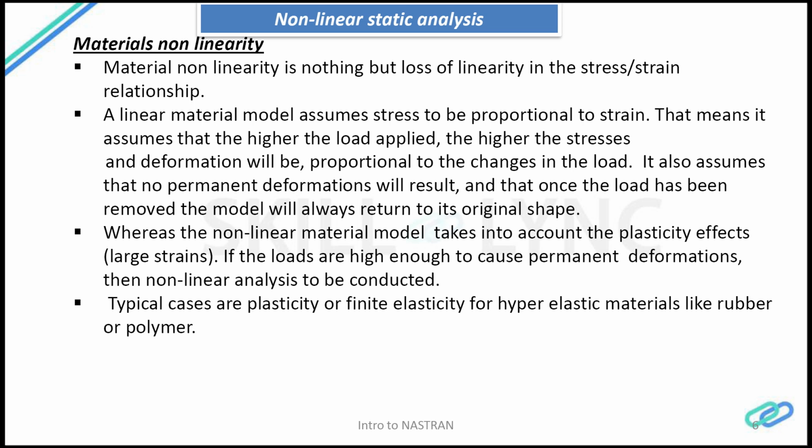Some people might be from an automotive background. For automotive cases, it's mostly nonlinear material, because they use soft cushions, soft rubbers, soft sealing rubbers, and mostly material nonlinearity comes into the picture.